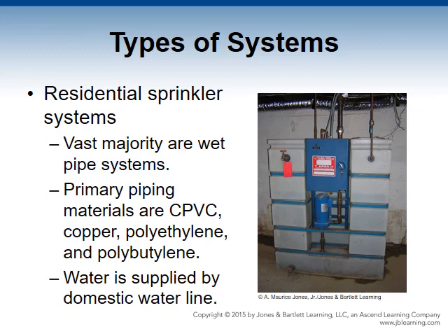Residential systems do not require sprinkler heads to be installed in certain areas, such as bathrooms that are less than 55 square feet, closets and pantries no greater than 24 square feet and no more than 3 feet deep, and garages. Open porches, carports, attics, equipment rooms, and concealed spaces are also exempt from having sprinkler heads.